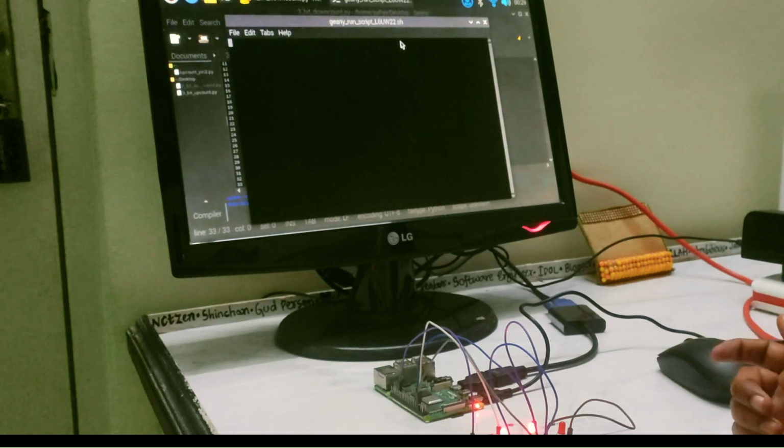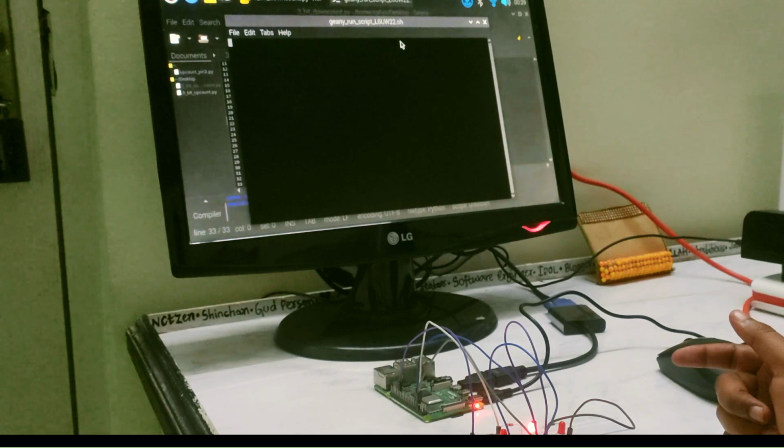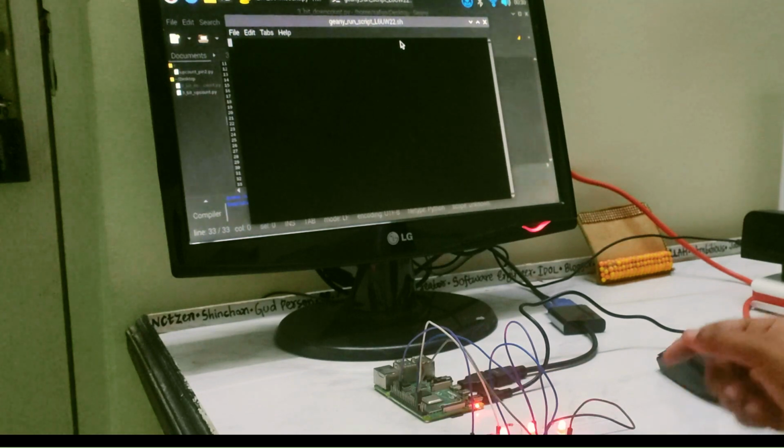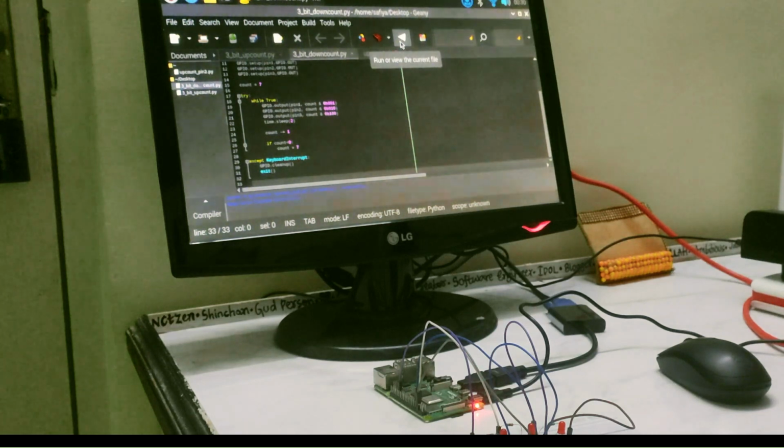Now when we run it, we see that it started from 7, 6, 5, 4, 3, 2, 1, and 0. The down count from 7 to 0 was implemented and the loop continued. And when I give Control C, we could exit out of the program without any issue. This particular program was executed by using GPIO 17 instead of GPIO 2. Hence, when I exited the program, none of the LEDs were turned on because it did not involve any pull-up resistors in the process.